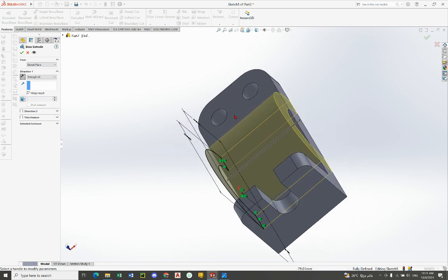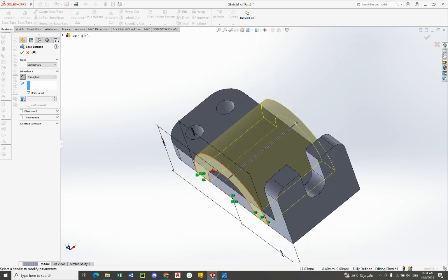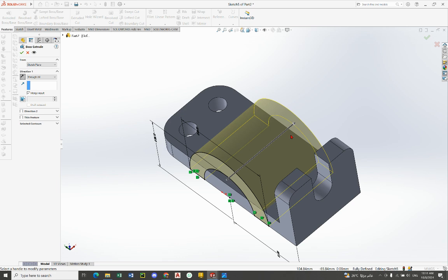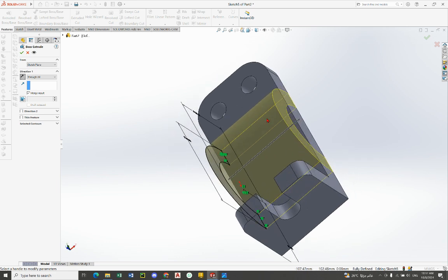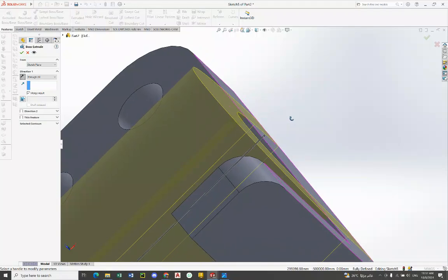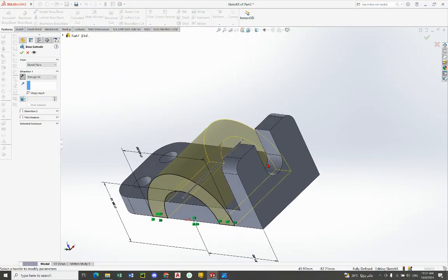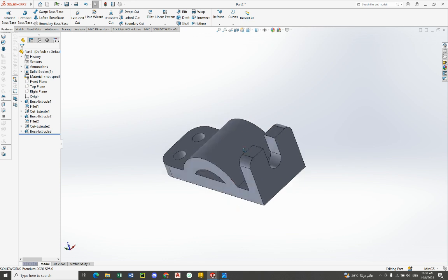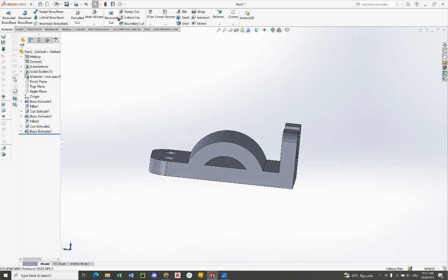It will take it as 48 millimeter because Through All in SolidWorks means through all the part, and the width of the part is 48 millimeter, so it will extrude it 48 millimeter. So it's perfect now. We can click okay here, correct, approve on the green arrow, left click. Okay, we have obtained it now.